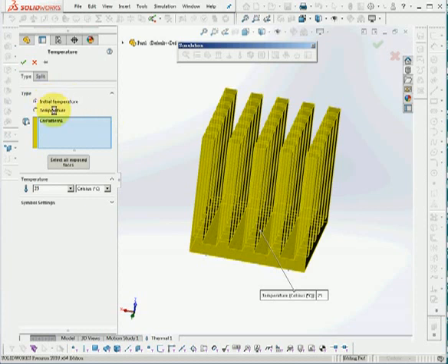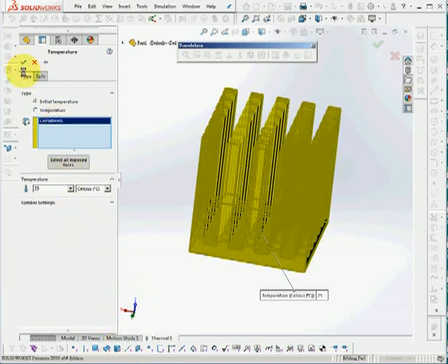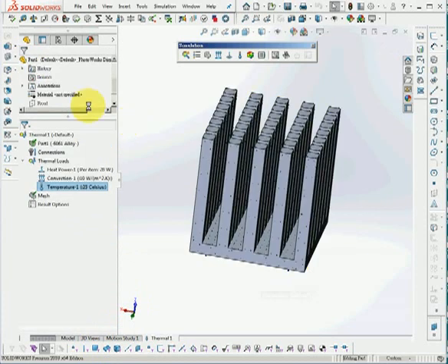If you choose temperature, it will be that temperature all the time. So you need to choose initial temperature, not clicking on this icon. Make sure that you choose body using the filter and then choose the whole body. Okay, if you do this correctly, then things will be good.